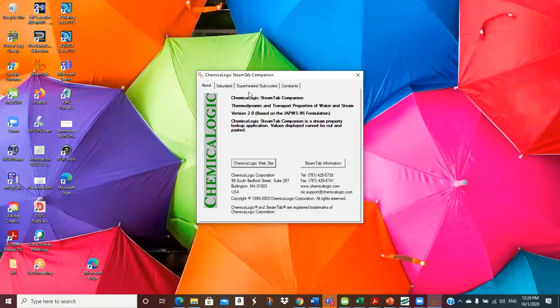Maybe, if you don't do the blowdown heat exchanger, you could do this, because that blowdown heat exchanger is going to heat up the makeup water as well. So then it's a question of multiple energy sources. You can't dump them all into the same stream. If you don't have another stream, then you pick the one that has the best bang for the buck and don't do the other one. So anyway, that's pretty good.